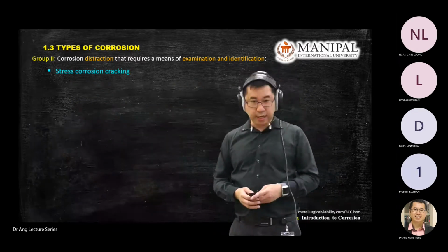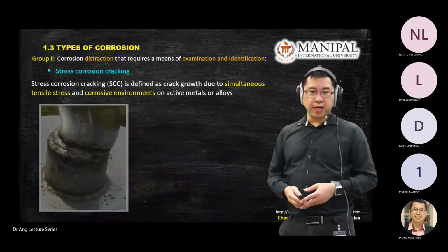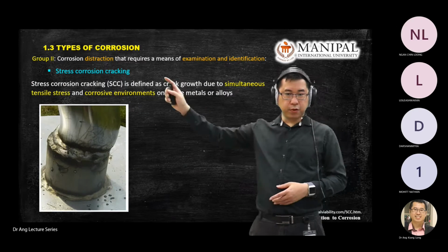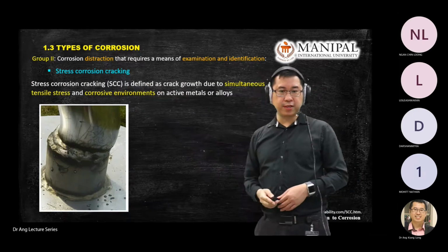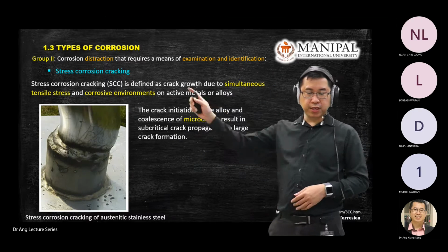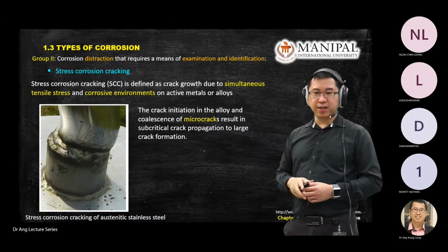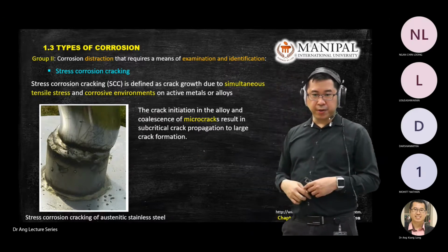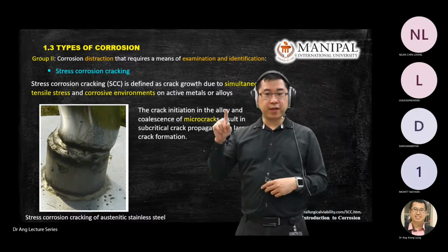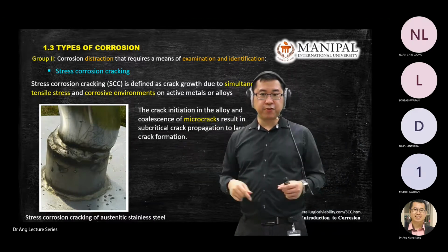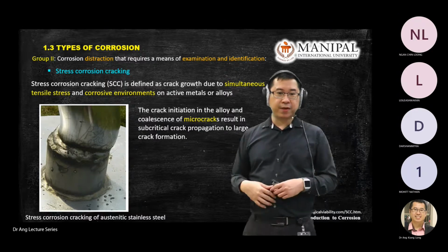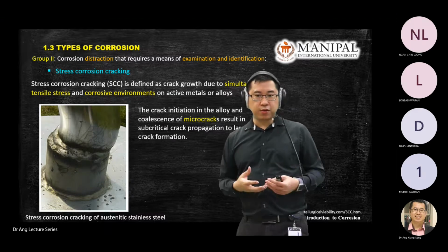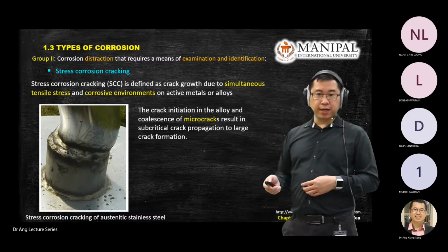So we have introduced a few forms of corrosion, and we'll go deeper later on for SCC. In SCC, we need two key factors: tensile stress and a corrosive environment. The corrosive environment means, since the beginning of the lecture, the general formula I gave you, right? So you need that environment. And sometimes the corrosive environment involves acid and ozone. So you need that. Okay.